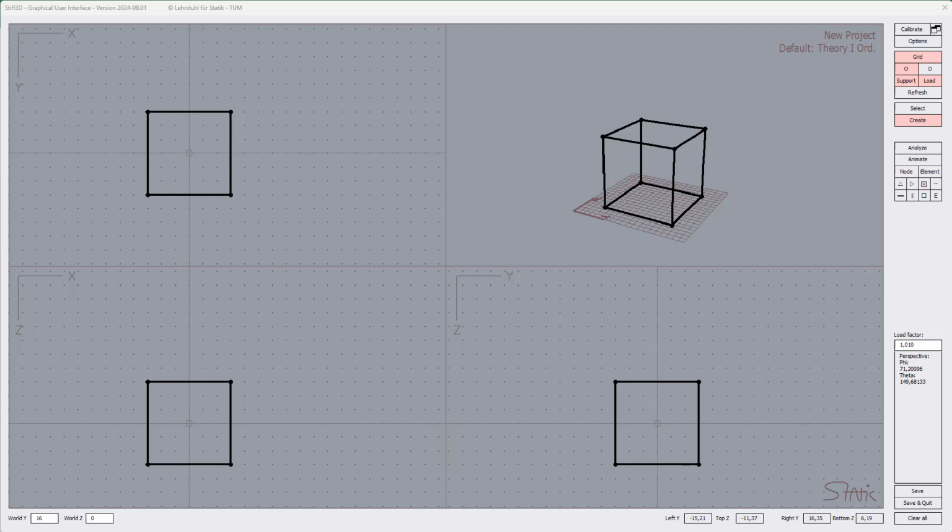Well, that tutorial is about how to move objects, how to copy and paste them, and to merge them. I have already prepared this cube here, this wireframe cube, by which we can nicely learn how to do that. Moving, merging, copying is something about modifying, and as I have mentioned already in the introductory course tutorial, modifying something is only possible if we are in the create mode. So you have to make sure that we are in the create mode, then it is possible.